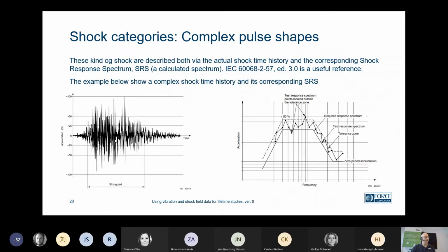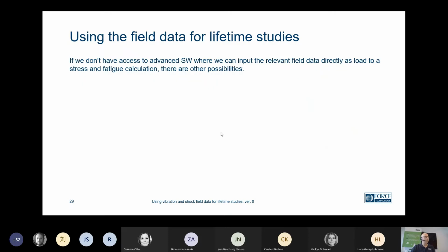And then you can calculate for a given time history in acceleration as function of time. You calculate basically how much different resonances will respond to this shock you put, and then you plot the maximum value as function of the resonance frequency that you look into, and you plot it as an acceleration at different frequency. That's a very short about shock response spectrum, but it's a good way to analyze the frequency content and get a good axis where you can read directly the correct acceleration value.